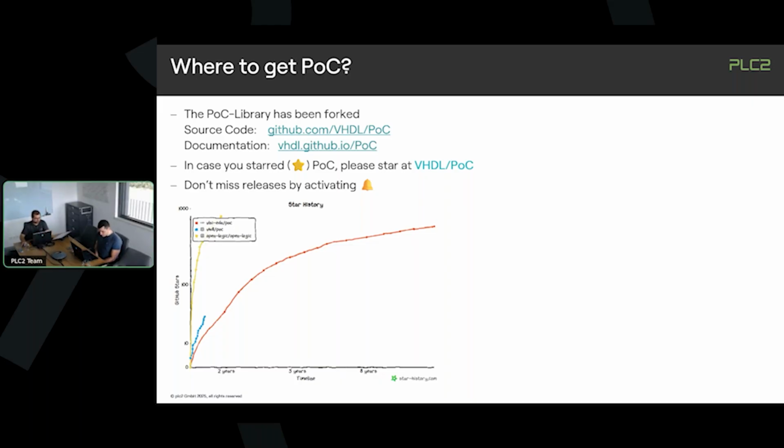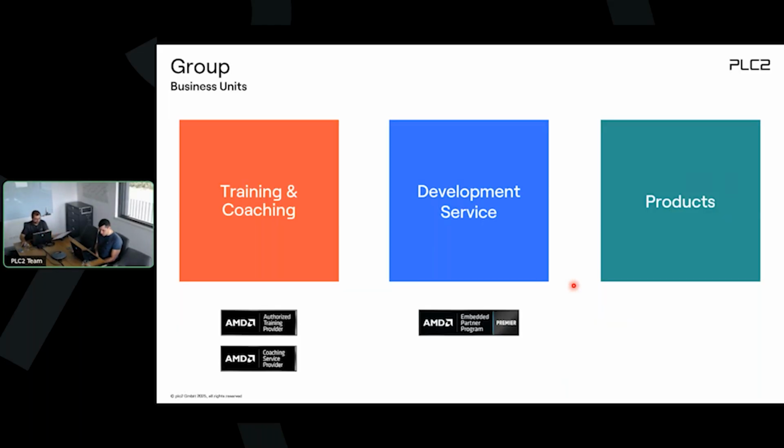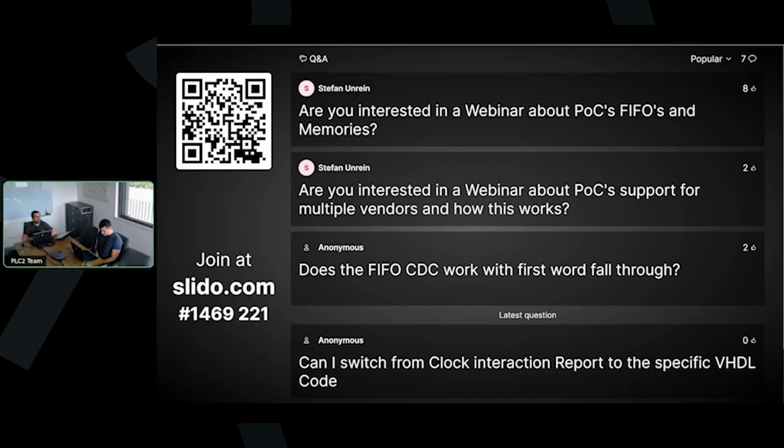Good. The next question, we have 2 left. What type do you use if you, for example, want to transfer an error counter across a clock domain where the individual bits are not independent of each other? So an error counter. If they're not independent of each other, so it's a counter, then it would be a sync vector to transfer to the other side, because then the whole integer value that's inside gets synchronized to the destination clock domain.